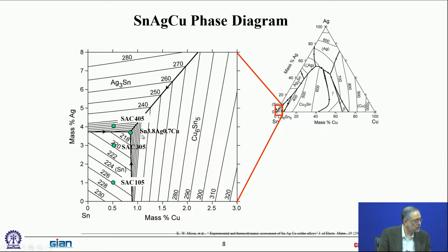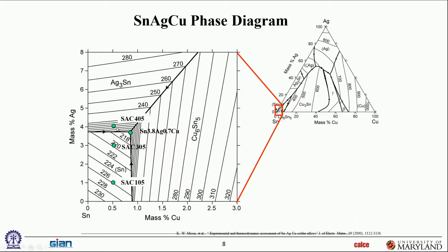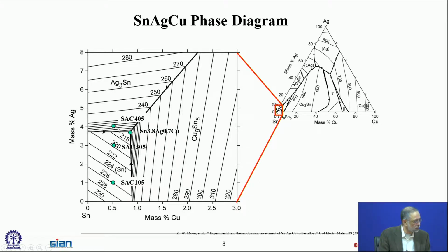no pasty range. But again, as I said, for a variety of reasons, we have dropped, well, some people actually used to use SAC 405, especially the semiconductor industry uses SAC 405 a lot, or used to. And partly because they wanted the higher melt temperatures, the temperature hierarchy that we've been talking about, because they didn't want solder joints inside the component to melt when the board level, second level reflow was being done. But it causes a lot of problems with excessive silver tin intermetallic, so that's a known problem.